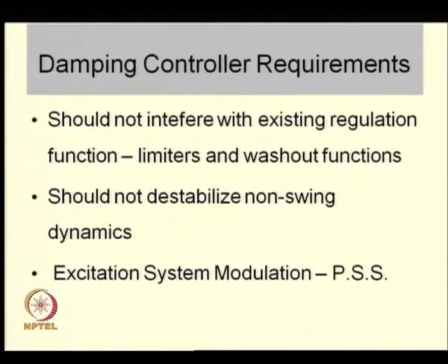It should not compromise on the basic regulation functions which are already there. For example, if you have an automatic voltage regulator in a generator excitation system, you would like to still continue with the same function. So, if any augmentation is to be done, then we should limit that augmentation.